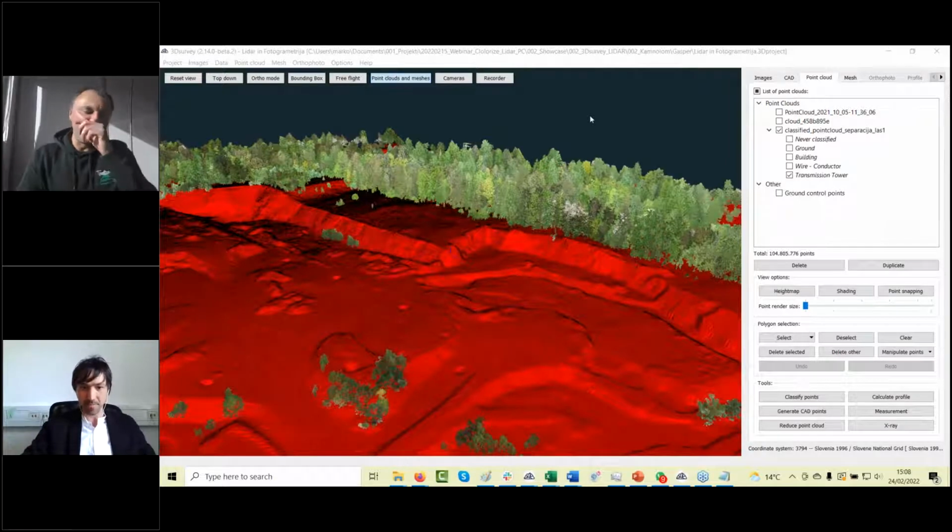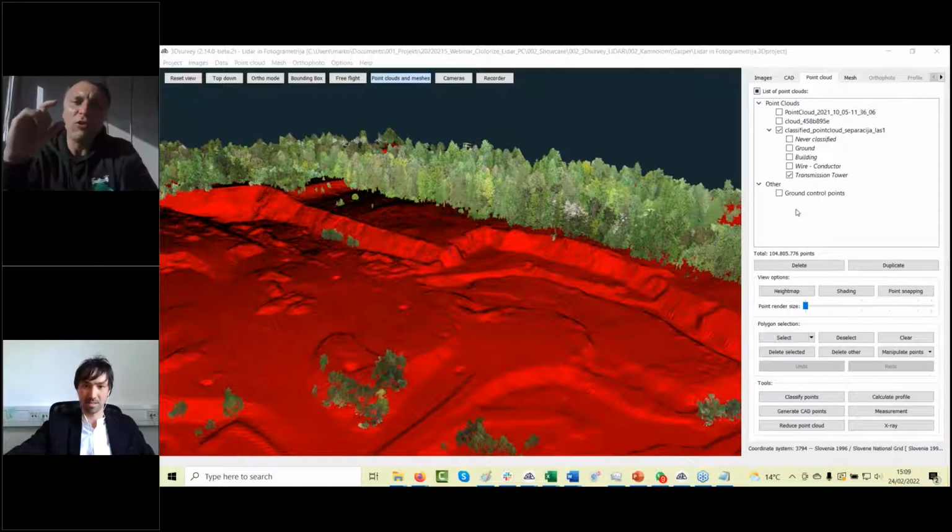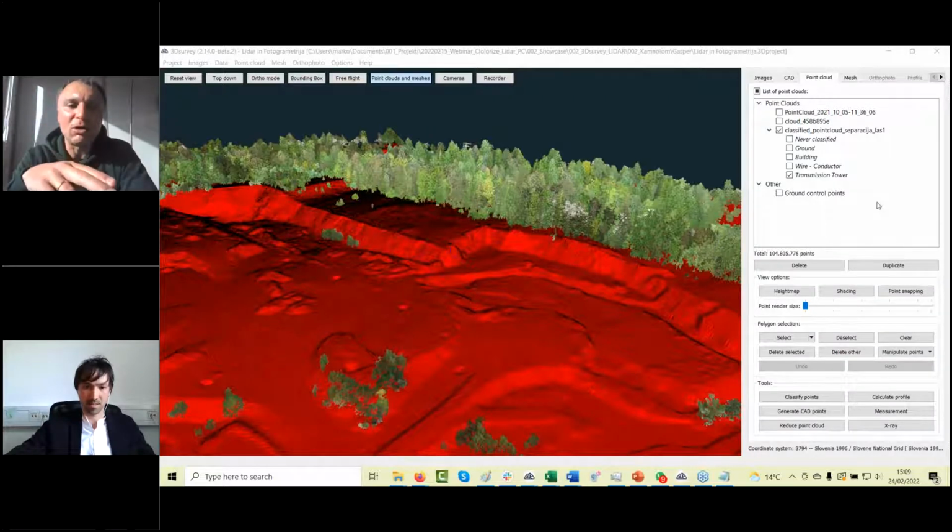Exactly. And I would say the Mavic Mini has the best opportunity for photogrammetry. Why? Because the Mavic Mini doesn't have autofocus. It has a stable focal length. In this case, you don't even need to calibrate the camera, just add a precise focal length. It was tested two years ago, and it achieved very good accuracy.